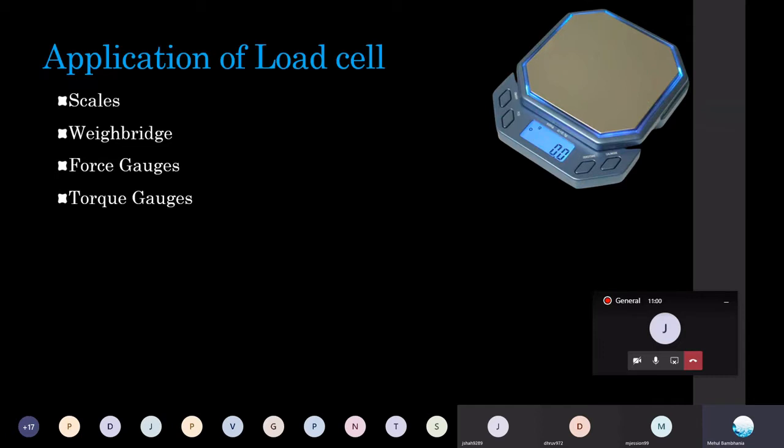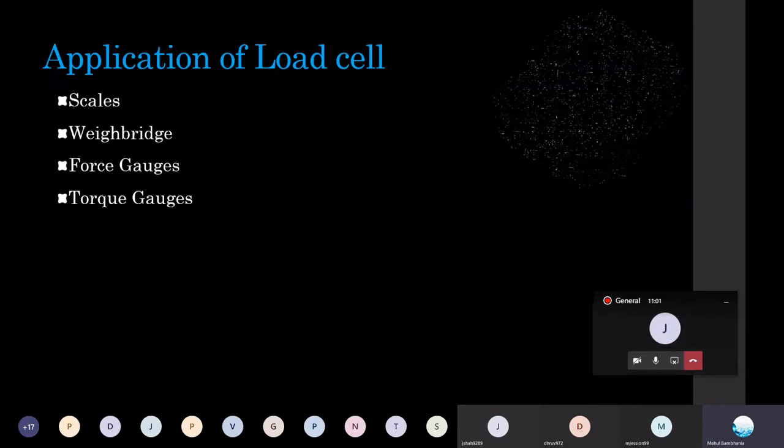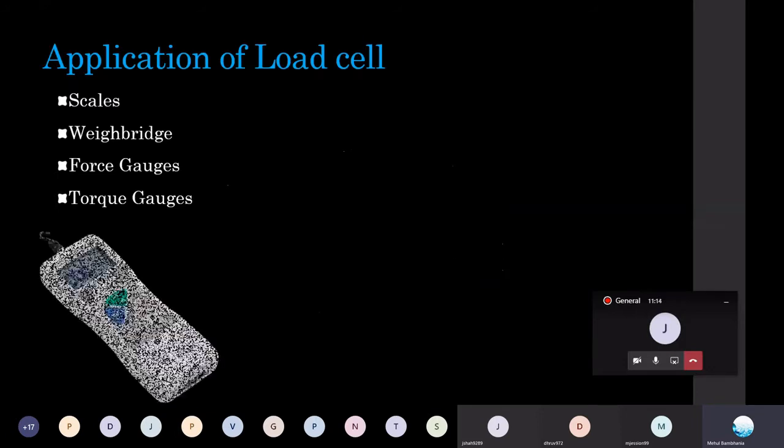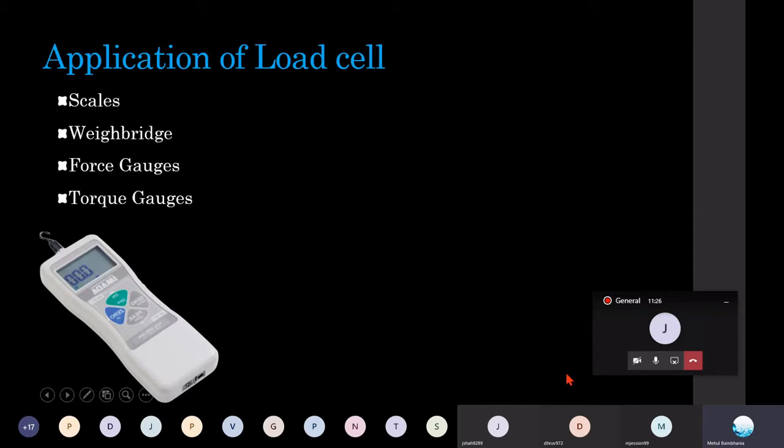That is the weighing machine or small weighing scale, but it is not restricted to small; on a larger scale, obviously, a weighing bridge also, this load cell can measure the total amount of force or weight or load. It is not restricted to weight measurement, but with the help of a hanging arrangement, we can actually measure the total amount of force acting on a particular hanging mechanism.